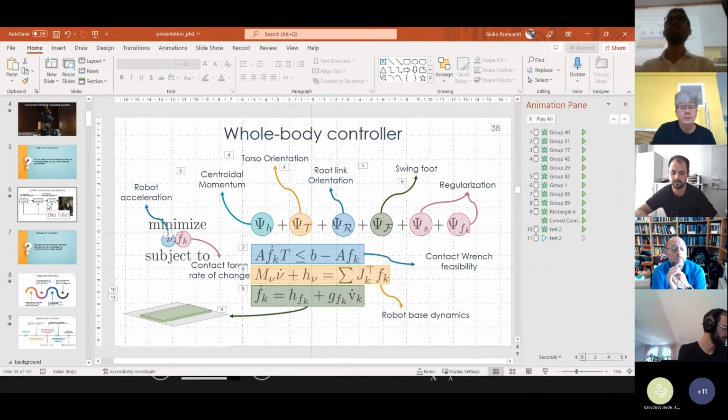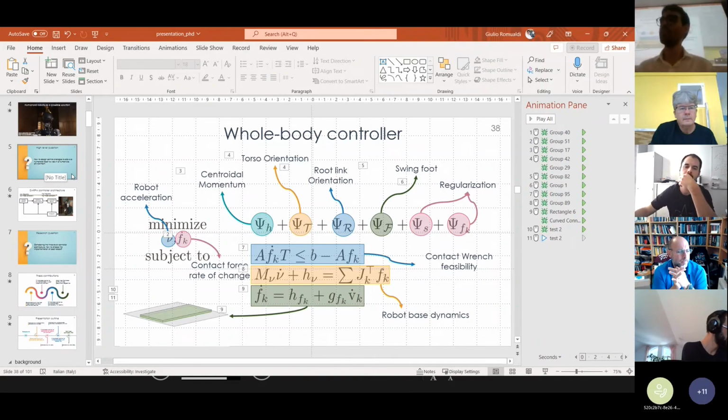In order to address this, we decided to move from the simplified model to the centroidal model. In the centroidal model, the ZMP will move while the robot is in single support, because the outcome of the MPC are the contact forces and the contact wrench of the foot.